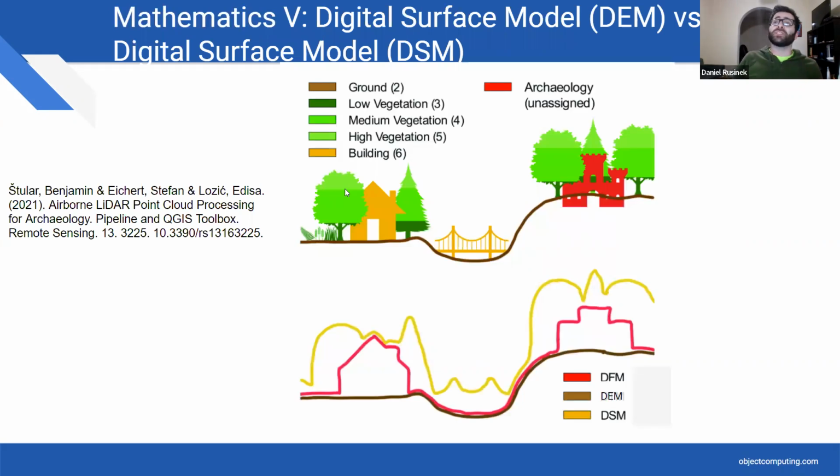So the result is either a digital elevation model, I got those mixed up, but yeah, digital elevation model and digital surface model. And you might sometimes hear digital terrain model. The nomenclature isn't all that standard. But essentially, a digital elevation model is this brown line here. That's when we talked about returns earlier. It's when you just do that interpolation using those last returns.